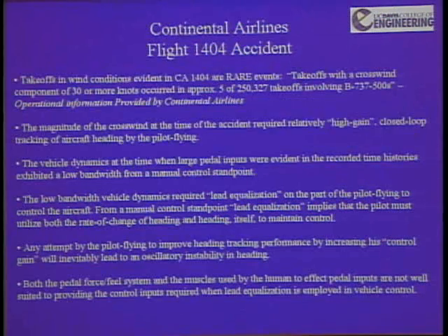So a whole bunch of conclusions here. Basically, the guy was really handed a difficult aircraft to fly. The crosswind gusting was right about at the limits for which the airplane is certified. The NTSB said, well, they need more training, and that's probably a good idea. When the guys come in for recurrency training, put them in the simulator and give them crosswinds of that nature, so they can become accustomed to the tracking.